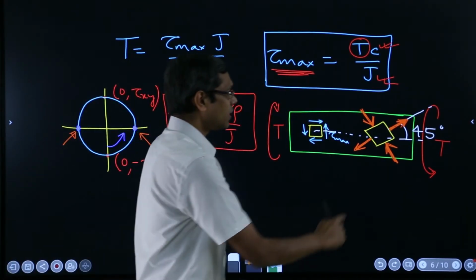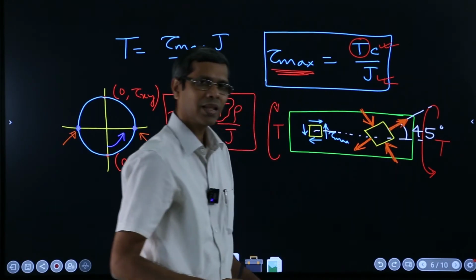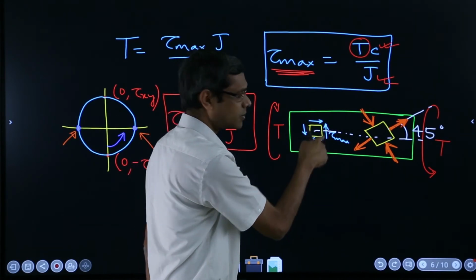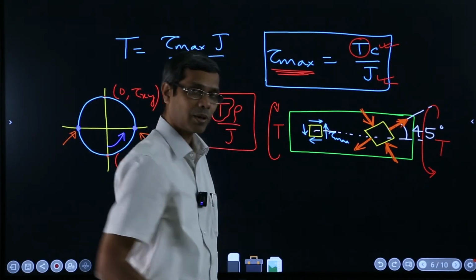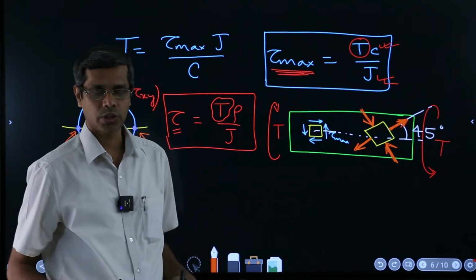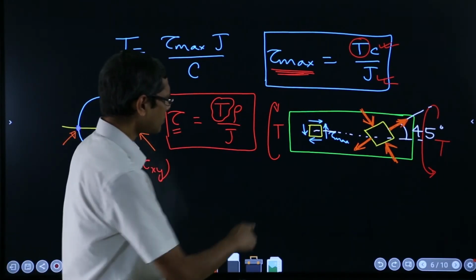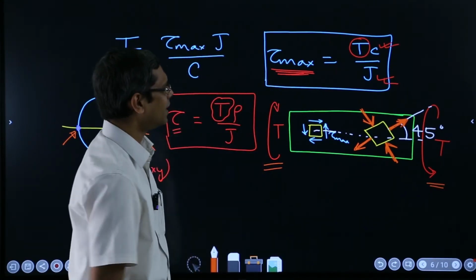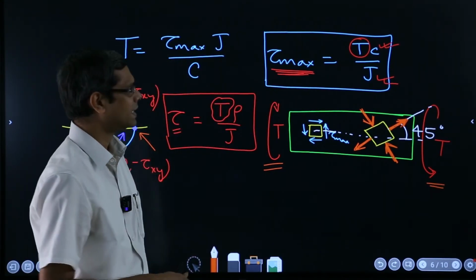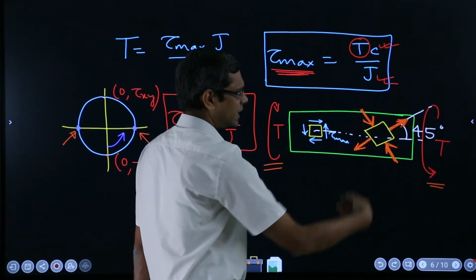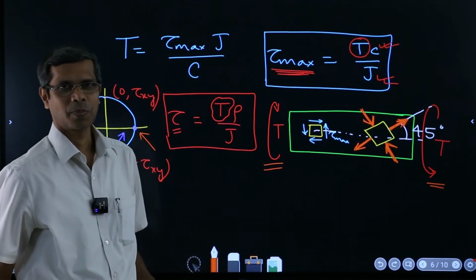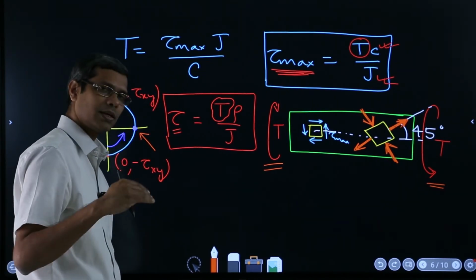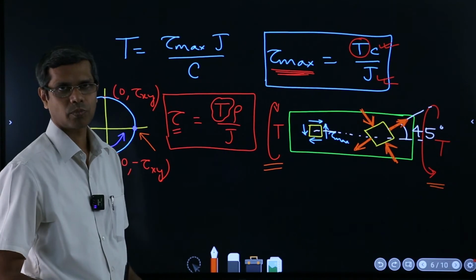And now you see that these kinds of pulls have resulted from applying these torques. We didn't apply any pull or push, we just applied a twist by using these torques, and in a particular direction, that is the 45-degree angle, the tensile stress got developed and the material is weak under tension, so it fails at that 45-degree angle section.